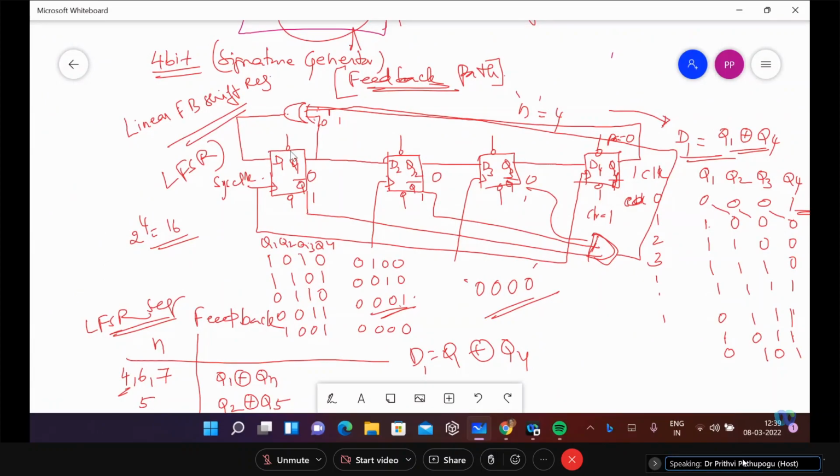This setup is fixed on a board or an IC. The moment you switch on the IC, there should be no manual interference. Automatically your circuit has to generate its own pattern, give that to the hardware, get the response, and compare that response, so the design validates itself whether it is working properly or not. So there won't be any external input.